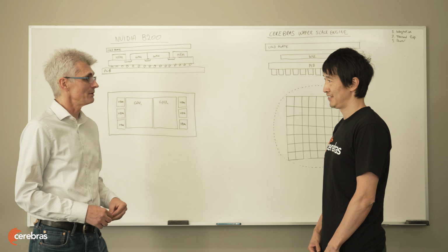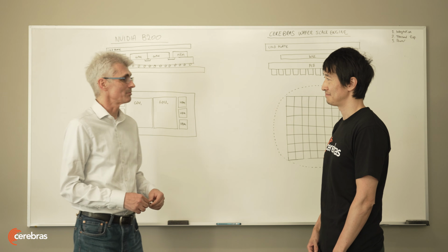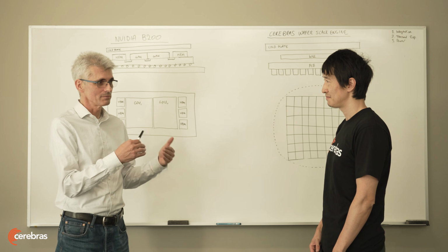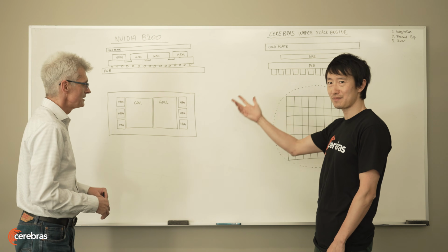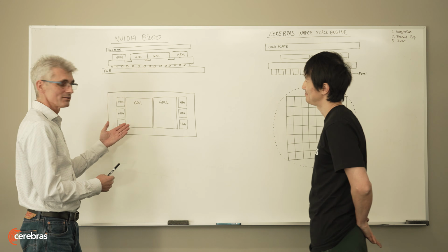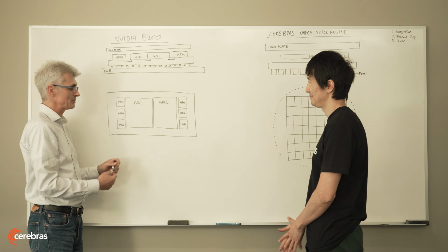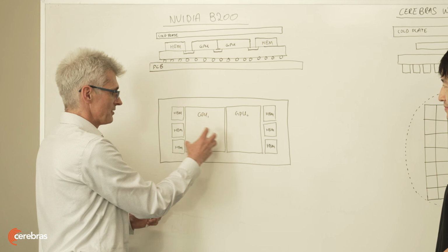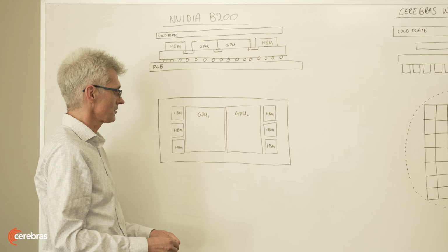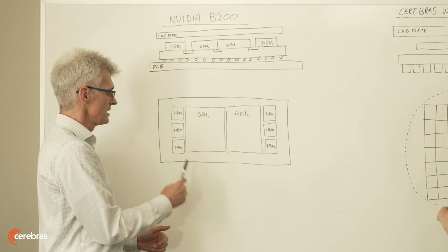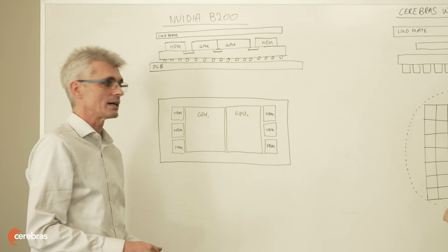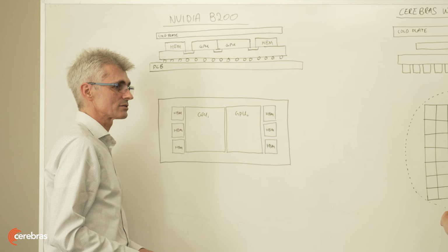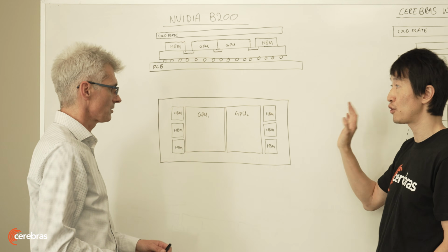It's a very tough problem to have those large processors on very large interposers. But maybe we should look at it a little bit closer to understand how an interposer is made. So here we have the floor plan of a package of a GPU, and in this case, you can see there are two logic die that are at the core of the processors, surrounded by multiple memory die. This is a typical package for such large processors. But previously there was only one GPU. Correct. Blackwell is the first to have multiple logic die.